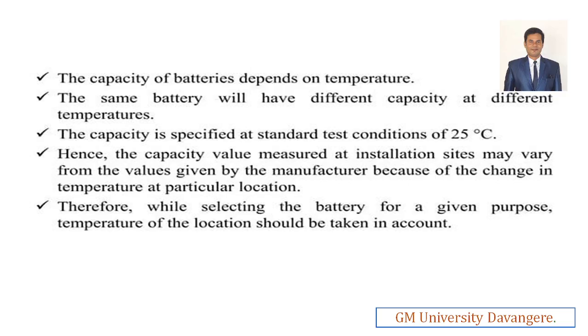Right, while selecting the batteries for any given purpose, please look at the temperature of the locations also, and it should be taken into account, right? Here in our state, the temperature may be very moderate. If you go to another state, the temperature will be very high. Especially if you go to West Bengal, the temperature will be more than 42 degrees centigrade. If you go to a state where the temperature is very low, like Shimla, it will be very low. So based on the regions, please try to select the battery ratings and also the battery for the purpose you're going to use it for. Right.